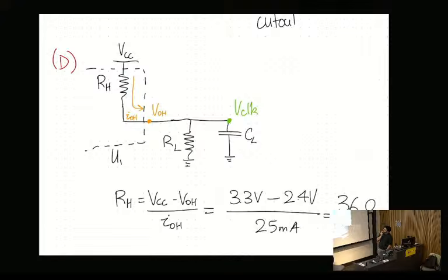That would give me the voltage drop across the resistor, but I'm interested in just one particular node voltage. Yep, there are a few ways you can do it. One way would just be voltage division. One way would be to take the voltage drop across the resistor, but now just look at what's happening to the right of the resistor. All of them would give the same result.